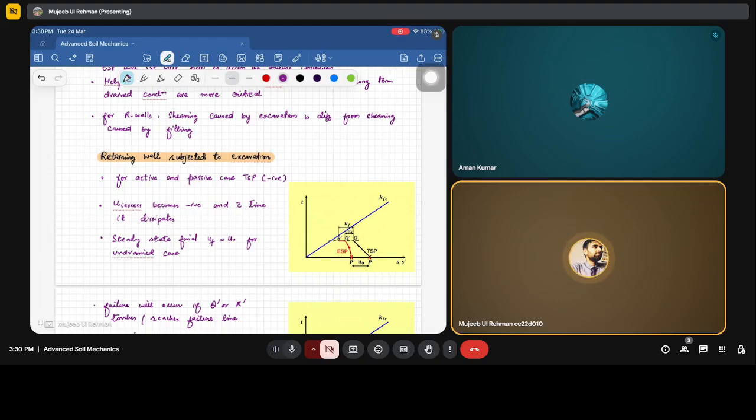So in that case, how is our TSP moving? Our TSP, see, what is T? T is sigma axial minus sigma radial divided by 2, and S is sigma axial plus sigma radial divided by 2. For example, if you're not changing the sigma A at all, so our slope is becoming negative, correct? Now this sigma R is decreasing, so it is minus of minus sigma R, so it means that T will be increasing, and this is decreasing, so S will be negative.